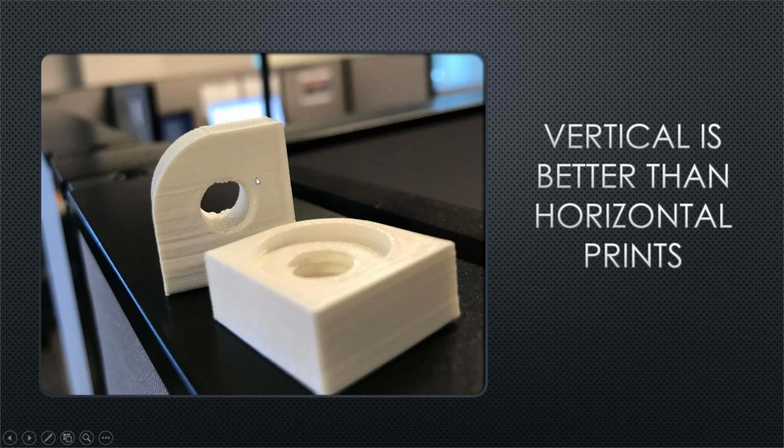But if you lay it horizontally, like the one on the left-hand side here in the back, you can see that there's a lot of discrepancy on this thread that occurred when printing it. And if you printed with supports, you would still have to break off the supports, and it leaves that kind of finish that you don't really want. So if you can, try to print vertically, but if not, then you're going to have to clean it up later on.